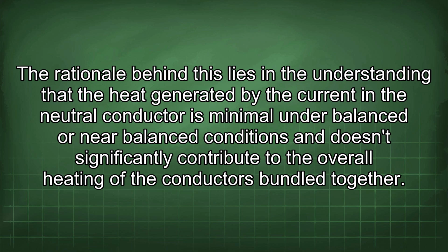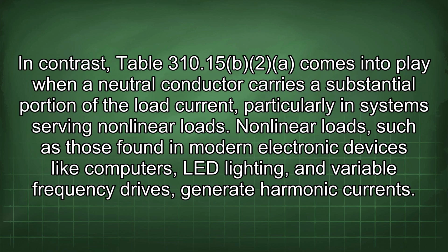The rationale behind this lies in the understanding that the heat generated by the current in the neutral conductor is minimal under balanced or near balanced conditions and doesn't significantly contribute to the overall heating of conductors bundled together. In contrast, Table 310.15(b)(2) comes into play when a neutral conductor carries a substantial portion of the load current, particularly in systems serving nonlinear loads.